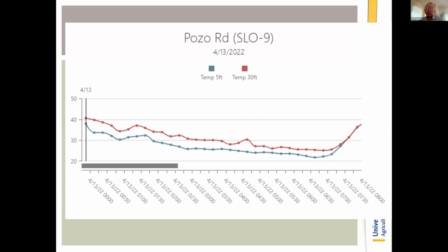Okay. So what I'm doing, all of my stations, they're installed far away from any wind machines because I want to see what the natural conditions are like that are not being affected by a wind machine. So again, I think that having that additional sensor, a lot of these wind machines now include a temperature sensor on the device itself to tell it when to turn on. So you could easily put a second sensor up high on the tower to give you that additional information.